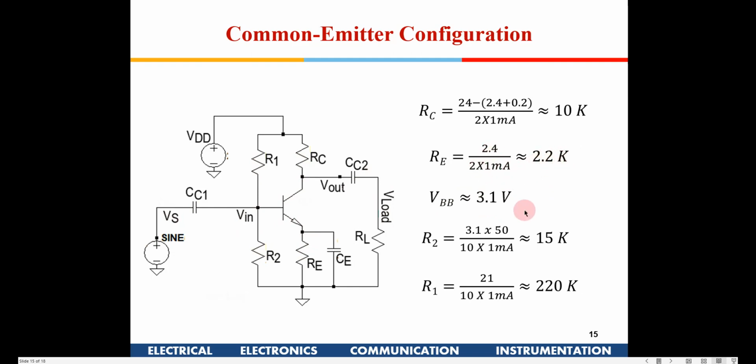So these are all just certain rules and tricks which you can use. Now if you see the voltage out here, it will be 3.1 volt, because 0.8 volt here, if you are allowing this to be in the forward bias region. Okay, 0.8 plus 2.4, or 0.7 plus 2.4, comes to approximately 3.1 volt. Okay, now what would be the current through R2? Now if you see IB, and this is 1 milliampere collector current.